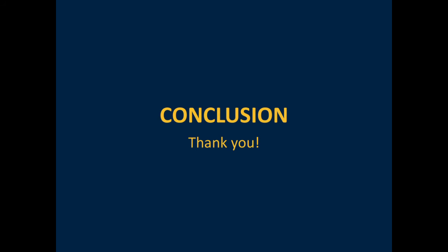We used BLE as a means of communication between the smartphone app and the device, and we implemented a custom distance measuring algorithm based on the received RSSI values from nearby devices. Finally, we implemented a geofencing feature using Google's third-party location APIs, where the app will be disabled within the selected geofence.